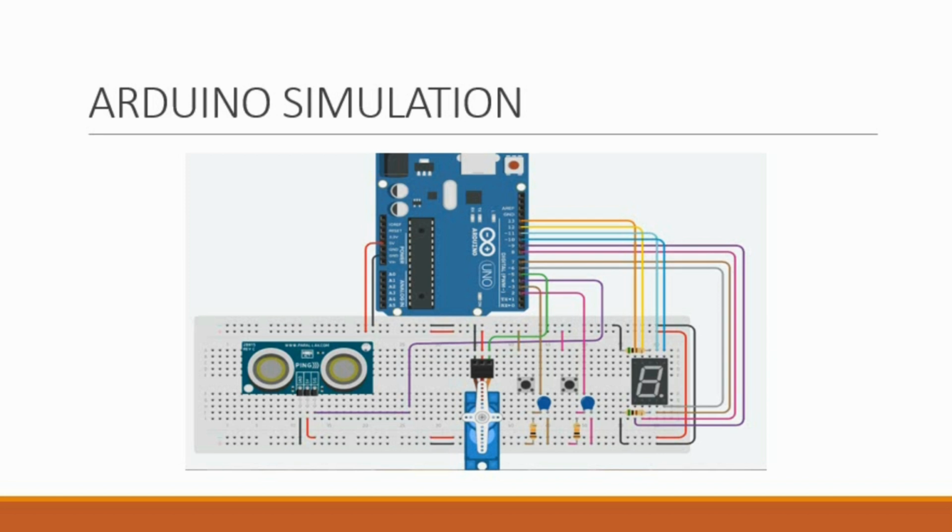To simulate the last stage of the machine and have it controlled via Arduino, we consider that photoelectric switch P2 is replaced by the parallax ultrasound sensor, and the palletizing system is controlled using the micro servo motor. Here is a representation of the Arduino circuit connections.